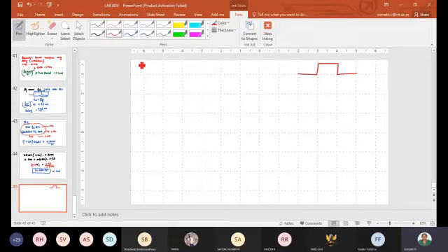So now what should I do? Let me use bit manipulation instructions. So complement P1.0. This we have to do once when the delay is over. I have to come here and complement the bit, and again go back to the delay calculation and complement the bit, again and again. Then after complementing, what should I do? I should call the delay. So let me use an absolute call, ACALL delay.